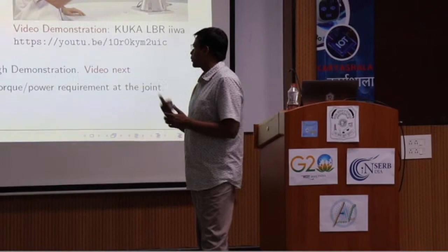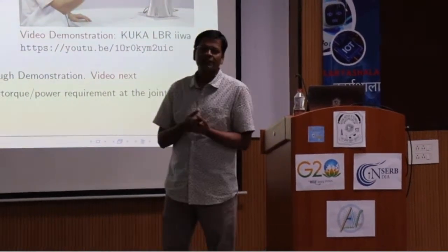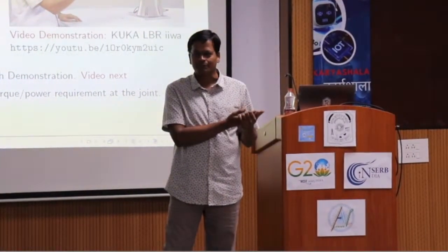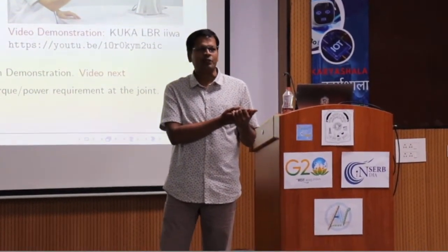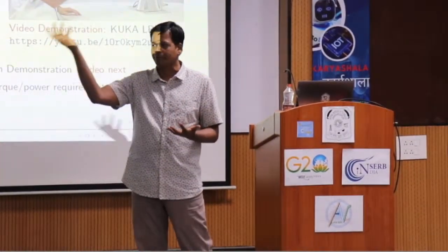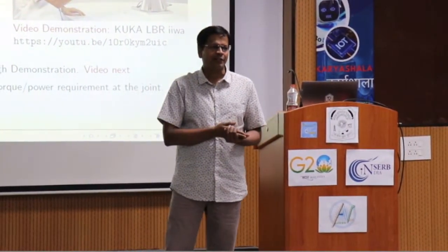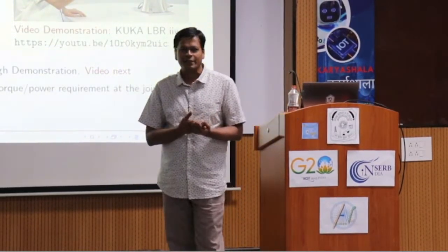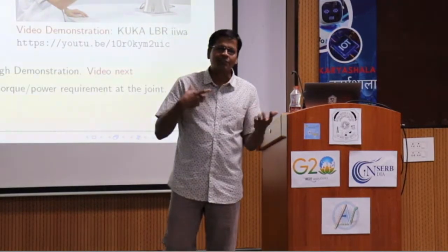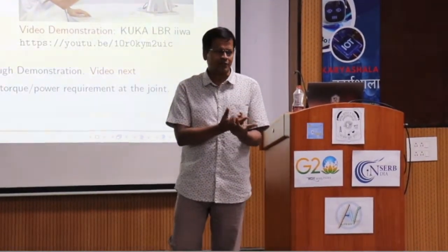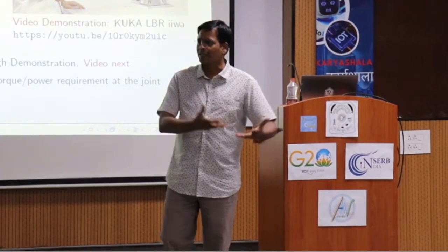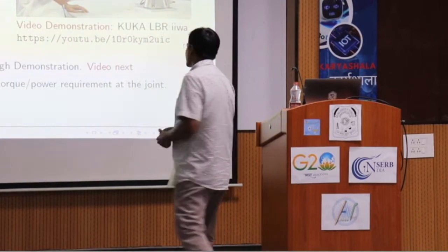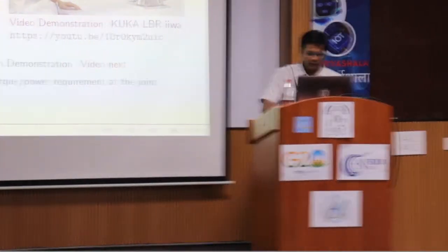So in this kind of robot, it is not there. But in case of industrial robots, normally they are gravity compensated in a similar way. But it is not always possible to do so because it is a very complex thing. Every place is different. Maybe at one place you are able to do so, but in all situations you cannot do that. Sometimes it is spring compensated. Springs are there, dampers are there, counterbalance is there. So there are mechanical ways of doing this also. So that is there in case of industrial robots, right?